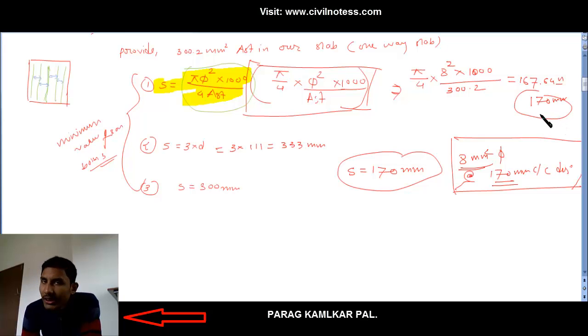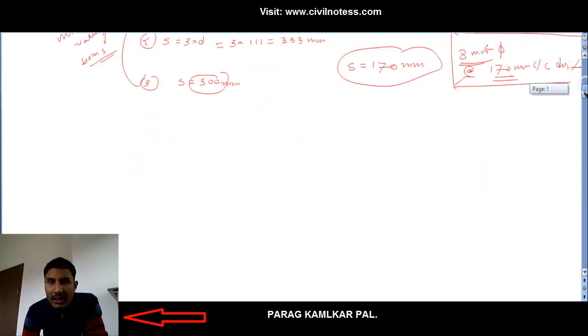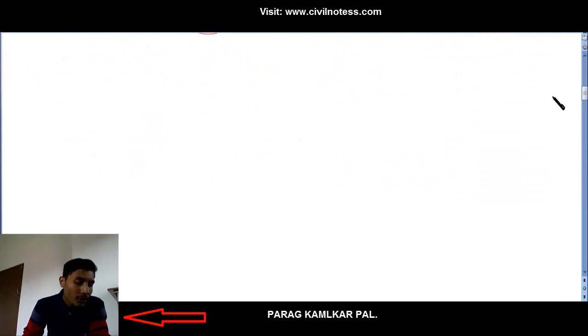Spacing is not bigger; its maximum is maybe 300, but along with the reinforcement steel you are going to provide, you have to take all the values properly. Now after the main steel, I wanted to provide the distribution steel also. So the design of the distribution steel is the next part. I'll take a different color for that.